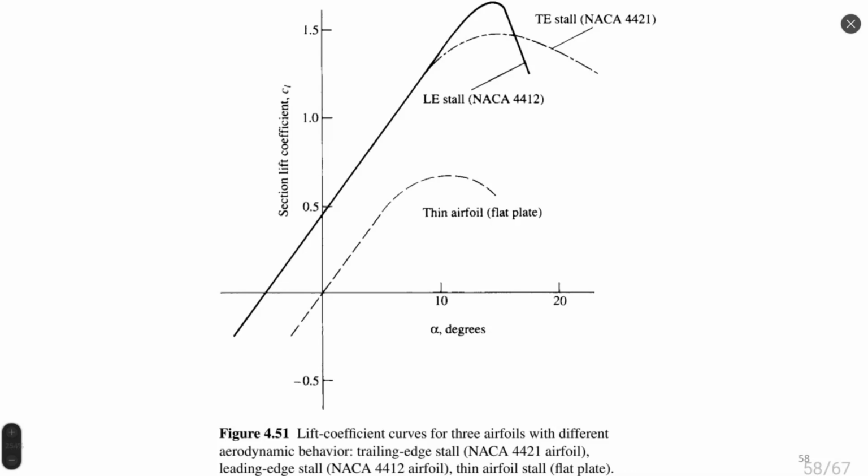We compare these two good airfoils. They are not the best airfoils, but they are good airfoils from a performance point of view. We compare with just a flat plate. We consider the flat plate as a thin airfoil. The thickness is very small with respect to the size of this plate. And using thin airfoil theory, we can predict lift coefficient.